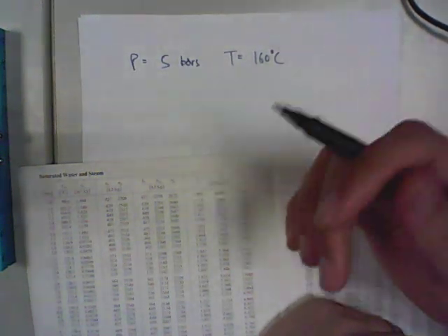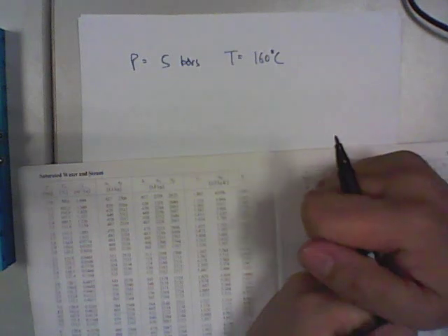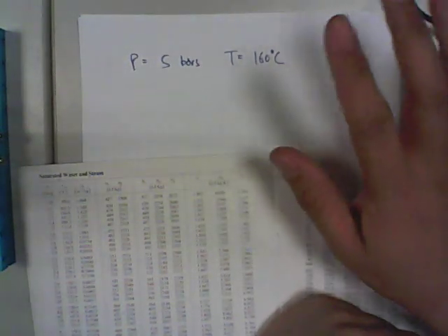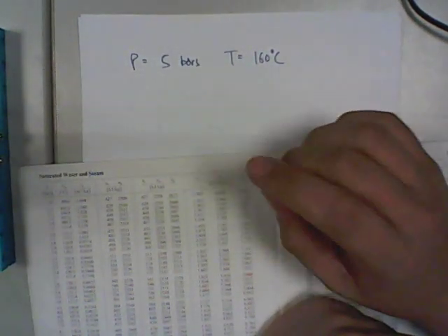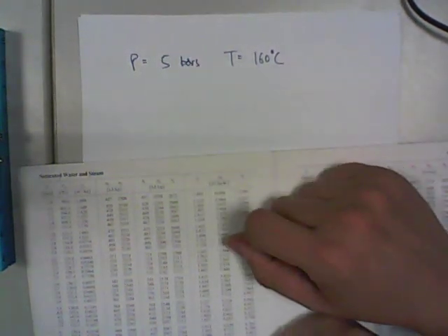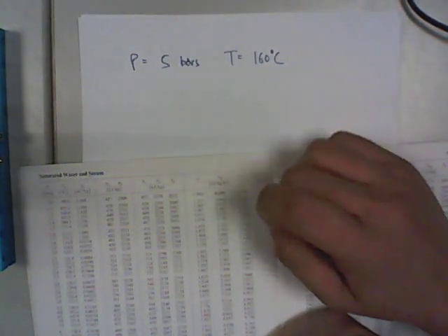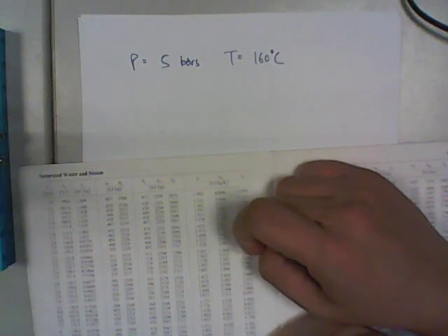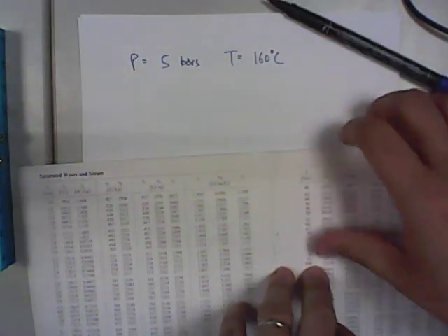On the phase diagram, the state of the steam can be determined if only two variables are provided to you. For example, if I give you pressure and temperature, you should be able to know roughly which region that state is at. Is it superheated? Is it wet steam? Is it subcooled? You should know. If I give you volume and temperature, or pressure and volume, you should be able to tell me which region it belongs to. Only when you know which region it belongs to can you fully make use of the steam table, which section of the booklet.